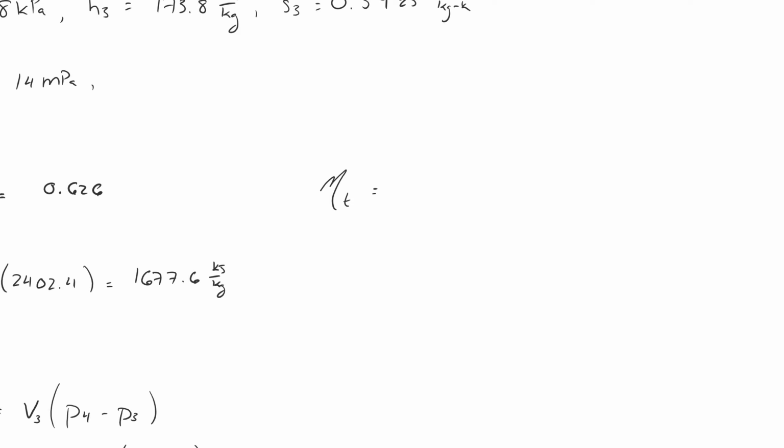Okay, so recall that your isentropic turbine efficiency is equal to (H1 minus H2) over (H1 minus H2S). But of course, nothing special about these numbers. That just happens to be how our cycle is labeled. And when you're trying to figure out which difference you should put in the numerator versus the denominator, remember that the larger value should always be on the bottom.